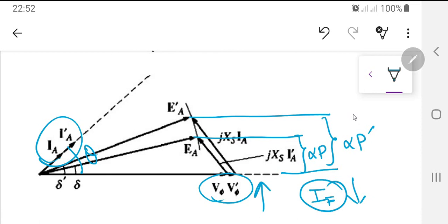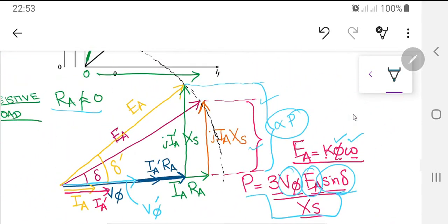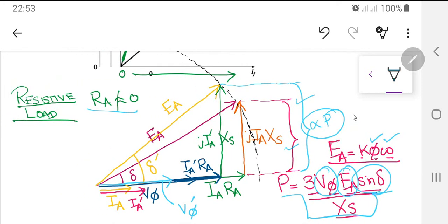One thing very important for loads: if you run a 220 volt fan or a 230 volt fan at 200 volts, maybe it will work a little slowly, because the current is going to be small and the flux is going to be small. But if you give a 230 volt fan 250 or 260 volts, you are going to burn down the insulation. So it is very, very important that your voltage is under control, and that's why a synchronous generator working alone is never the solution. Whenever we have a synchronous generator working, we always have it in parallel with other generators, or the other word used for it is the grid, which we will talk about in the next lecture. It is very important, because this is how the paralleling of generators on the grid is done, and that's a very difficult process which takes some time.